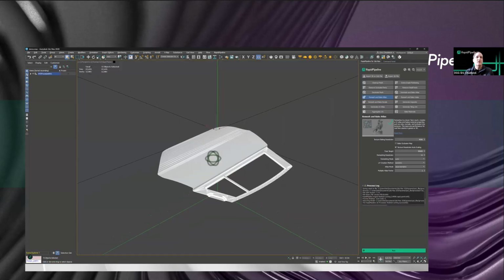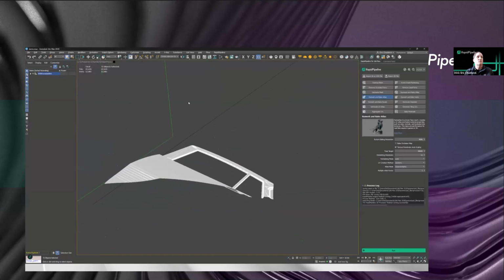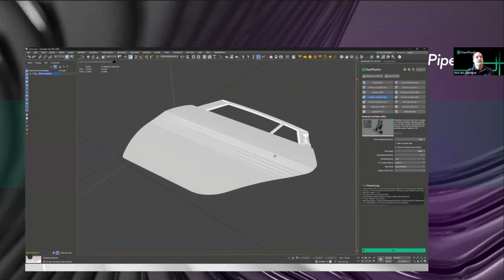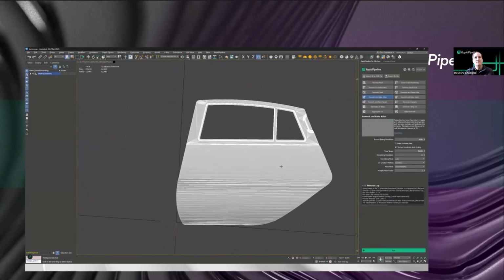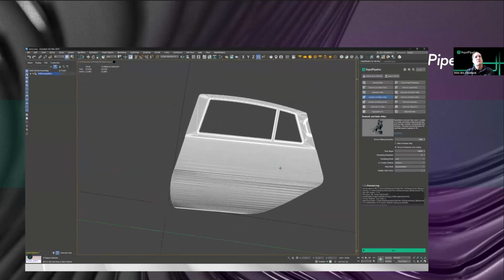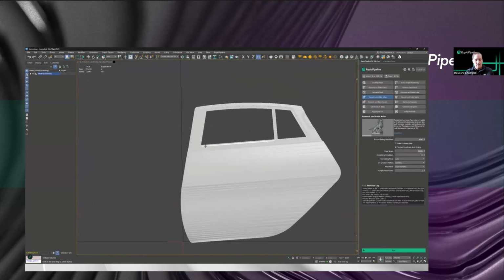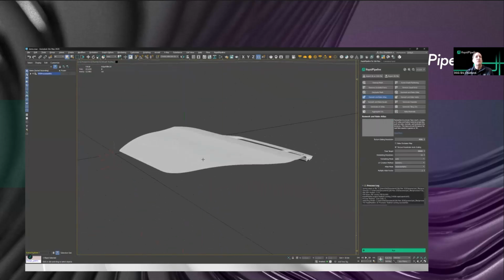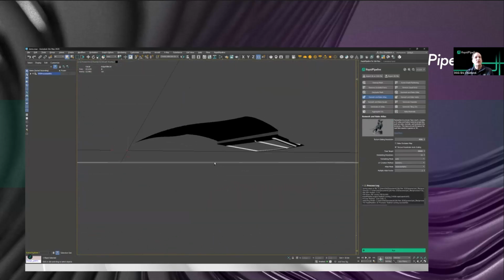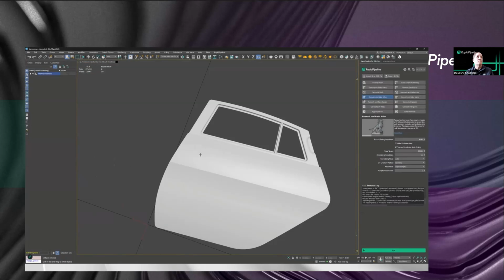Oh, let's see, it's fairly small in Max. So we're going to need to turn on viewport clipping because it's under a unit, I think, in size. I have my unit set to meters here. So it's pulled it in and it's tessellated it. And this model is flat on the floor, so first of all, that's something we probably want to fix. And then it's made up of 73 different meshes here.